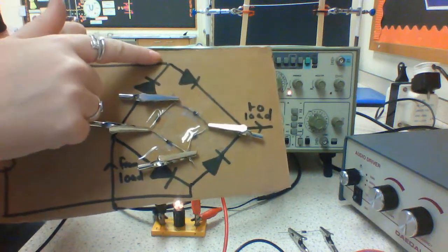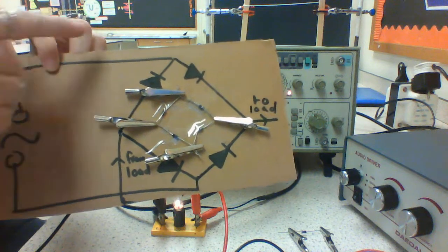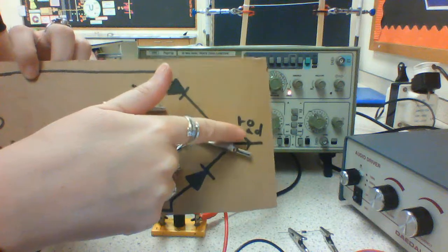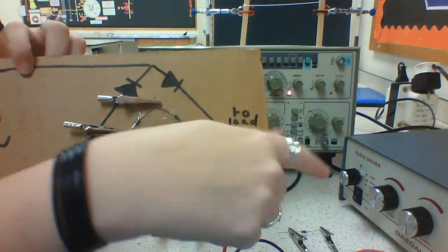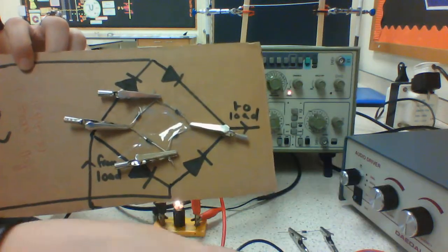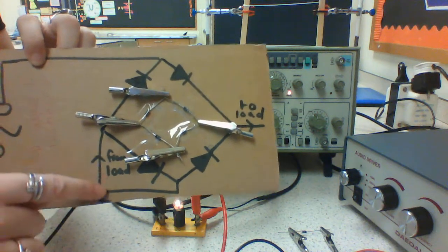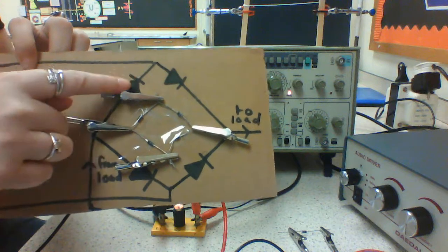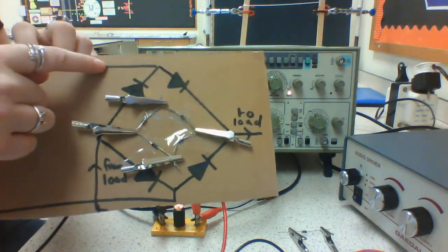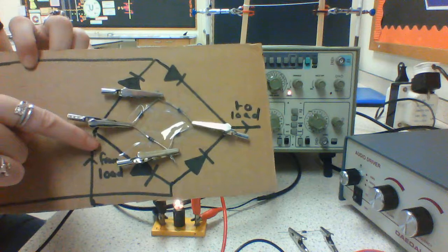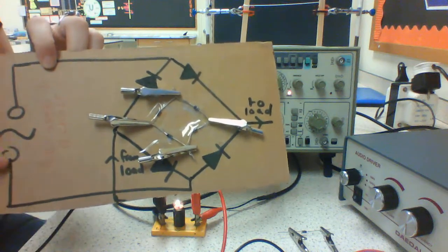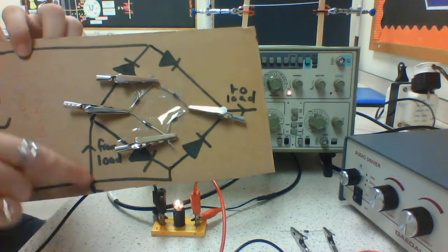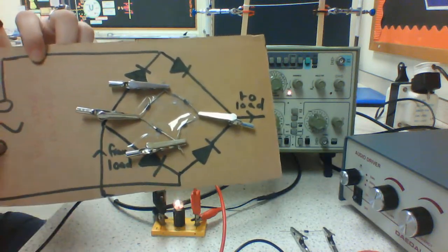But here, if I were to say the current is going to flow up and around, which it will do every half a cycle, it can only flow through this diode and then out to the load. It'll go through the load, which will be my bulb. It'll come back from the load, and it'll flow here. It's got a choice of which diode, but it's not going to go through this one because the current's flowing this way in this half cycle, so it won't flow that way. But it can flow here, and it will flow back to the power supply. So every half cycle it comes up, through the load, back down here, back to the power supply.